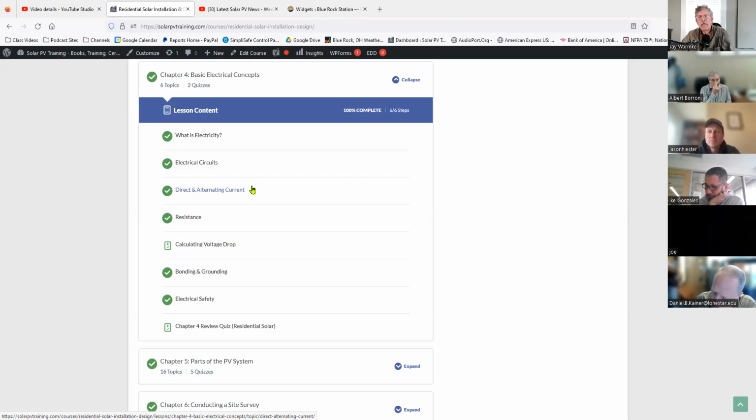We typically do series connections to get the voltage to whatever voltage requirement our loads need. You know, in a standalone system, if we've got 48-volt light bulbs or something, we need a 48-volt power source. So I might hook 4 12-volt batteries together in series to get to that 48 volts. Then I hook things together in parallel to get more power over longer periods of time.